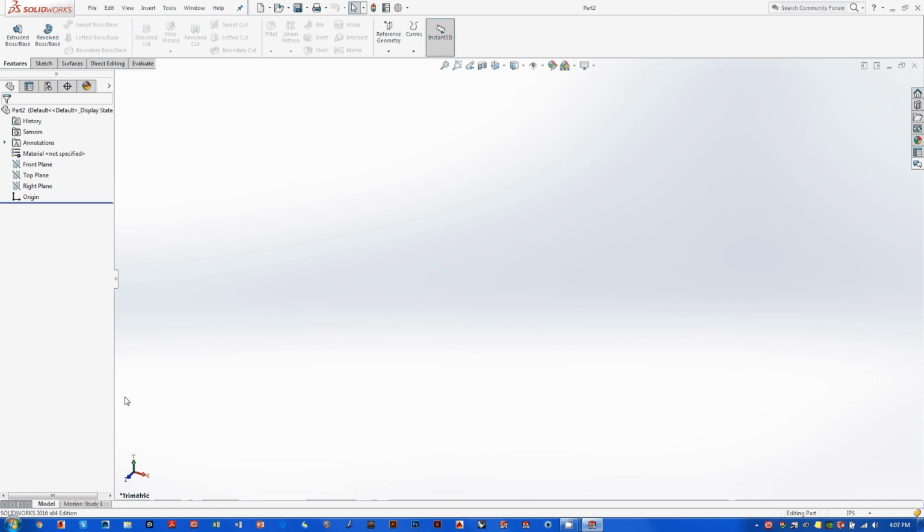SolidWorks is one, another would be Rhino, and then you've got Alias and ZBrush and Maya and a bunch of others that you can get into. All of them are set up in different ways. SolidWorks is specific in that it is a Y-up axis program. So you'll build your model on a ground plane with the Y-axis pointing up.